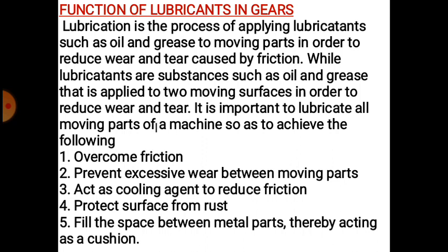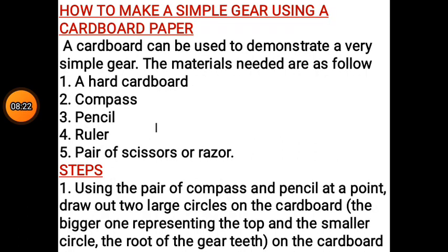1. Overcome friction. 2. Prevent excessive wear between moving parts. 3. Act as a cooling agent to reduce friction. And number 4. Protect surfaces from rust. 5. Fill the space between metal parts, thereby acting as a cushion.